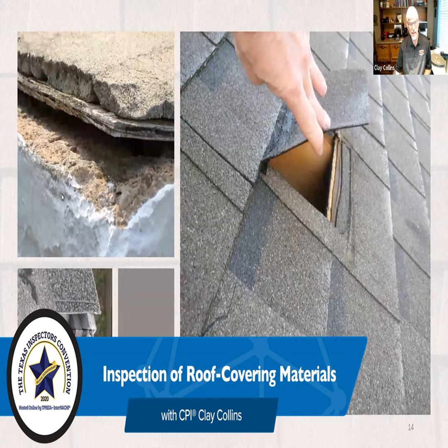And then here, that looks like, frankly, somebody came back and said, well, I've got an extra nail, I'm going to put it right here after the shingles are done. And then here you have the same thing exposed. So none of these were put where they were supposed to be. And then you have the problem with whether they actually installed the nail correctly itself. A lot of times you can see the impact of this, mostly with an underdriven nail.